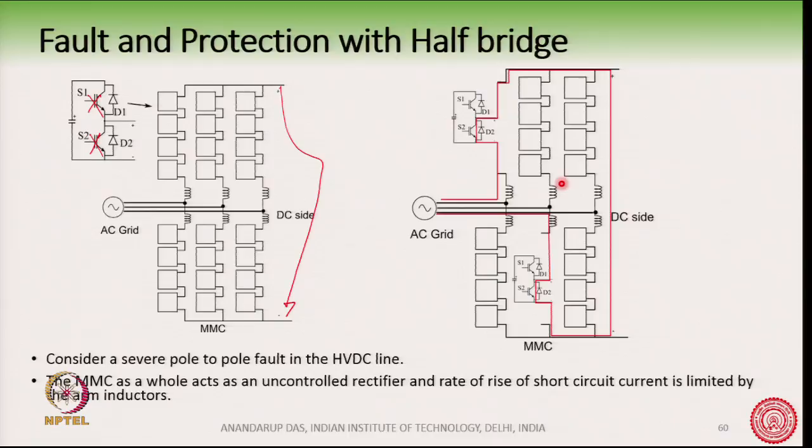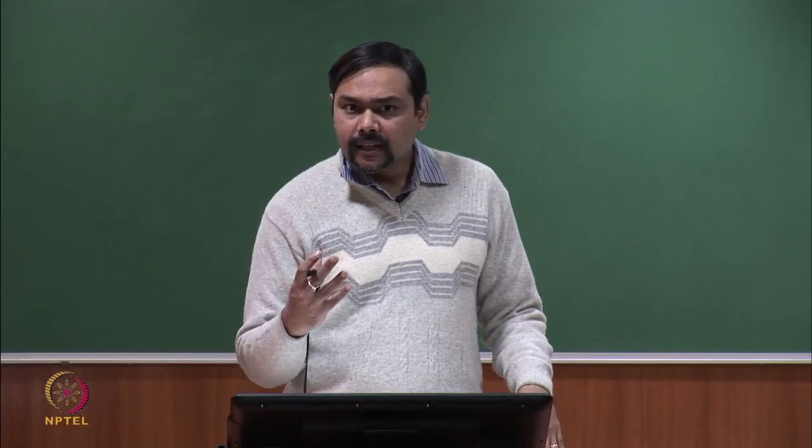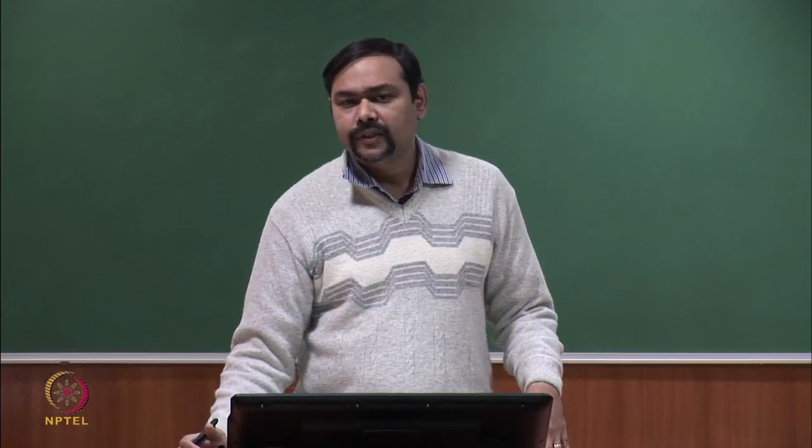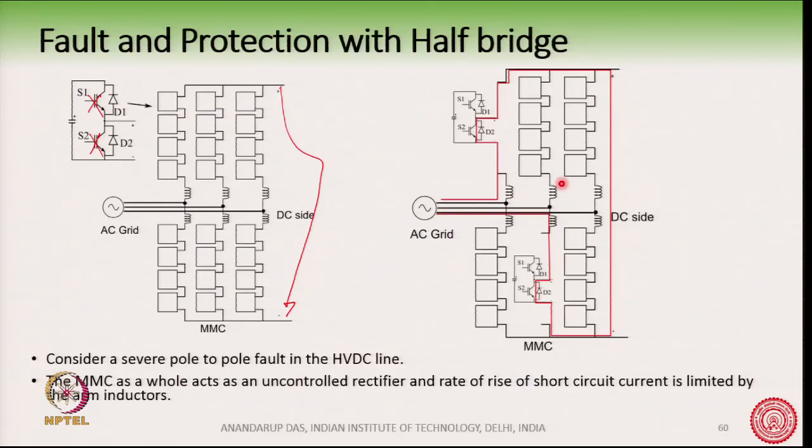Okay. So, using an air core inductor, we get less inductance per unit volume, but we can avoid saturation of the inductor during this time. Often these arm inductors are air core inductors to avoid saturation, but of course, the penalty is the size of the inductor is very big. With an air core inductor, the inductance obtained per unit volume is much less than when you use an amorphous core inside.